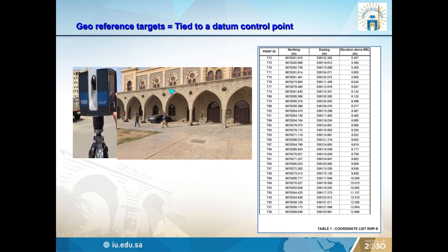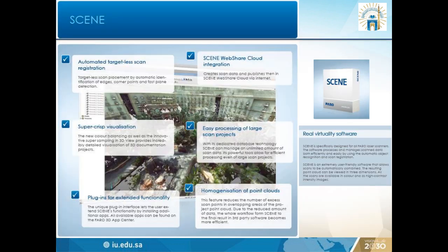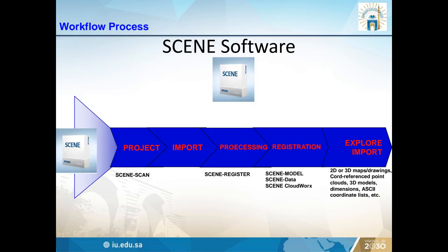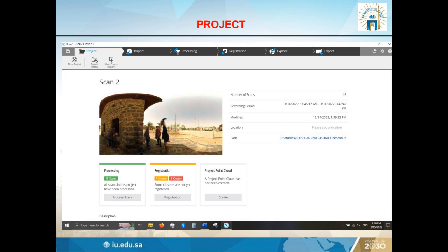And then we collect the data of each laser scan and we compile it in the Faro Scene software. So this is showing the Faro Scene software. This is very user-friendly software, and we capture the records, and this is a project created. Then we import the data, then process it, then register, and finally we export our drawings into different forms.